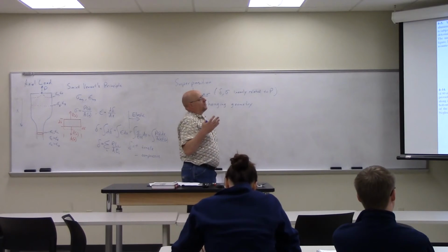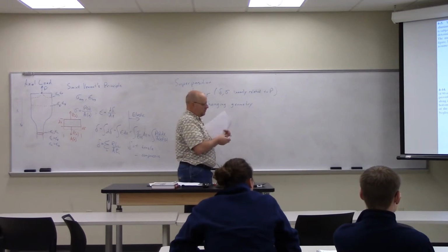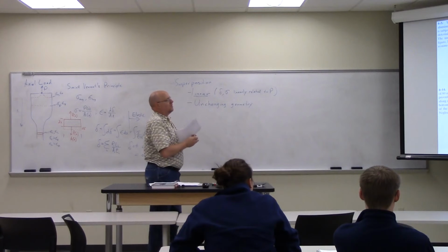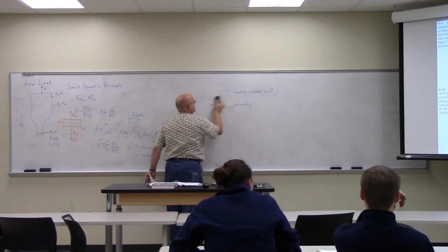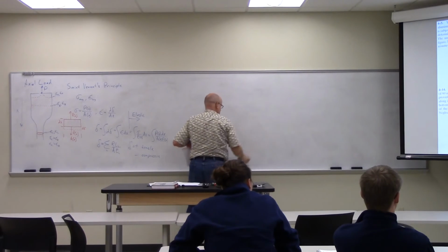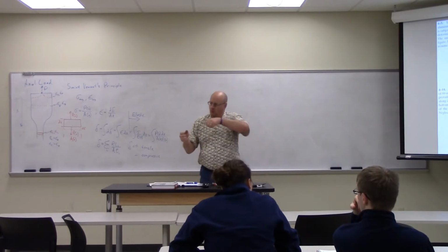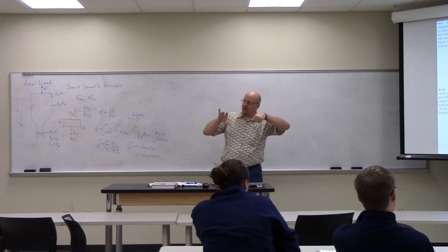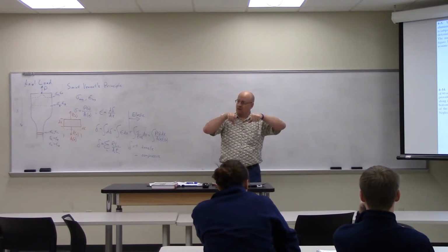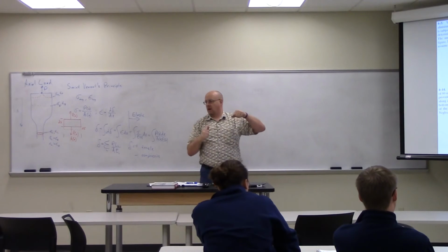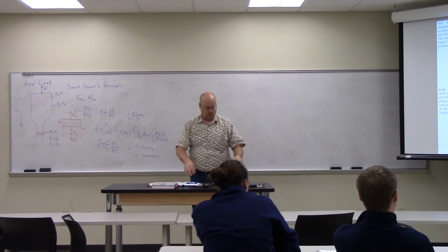Then we need to find the displacement of coupling B and end A. The dimensions given in the drawing are the undeformed, unstretched dimensions. Oh, so there's an actual second force on the coupling B, pointed towards the wall? Right, so there's one force pulling A out, and there's another. You can imagine a hollow cylinder riding on the outside of that shaft AB that is pushing to the left. Everybody understand the problem and how it's drawn?